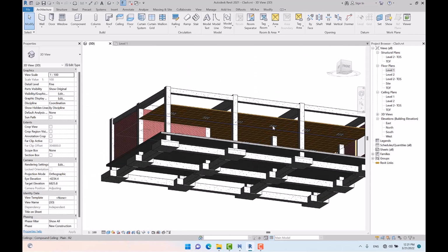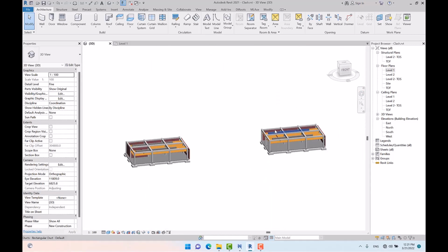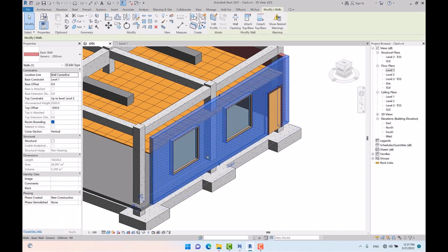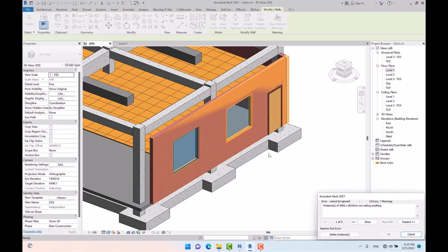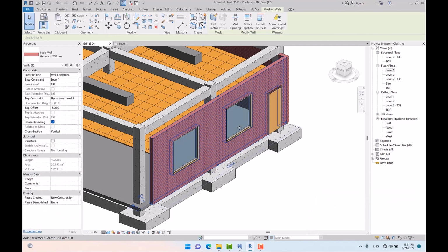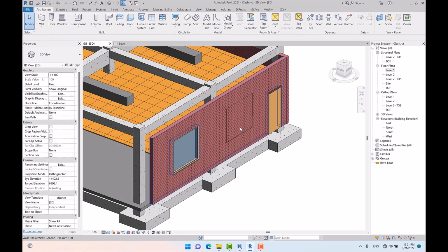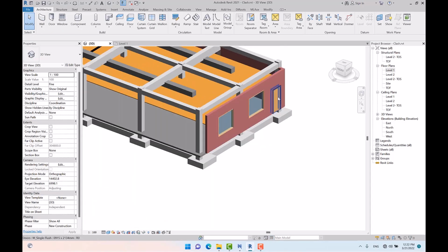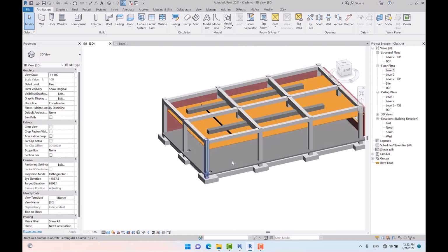Following that, we got some lights, but in the other model I want to make a copy from the selected wall this way, then I paste it aligned to the same place. Note that when you copy a wall or an object and then paste it aligned to itself, the doors and the windows will be pasted aligned to the same place. Here as you can see, I got two windows. So practically here we got two walls which are overlapping each other.